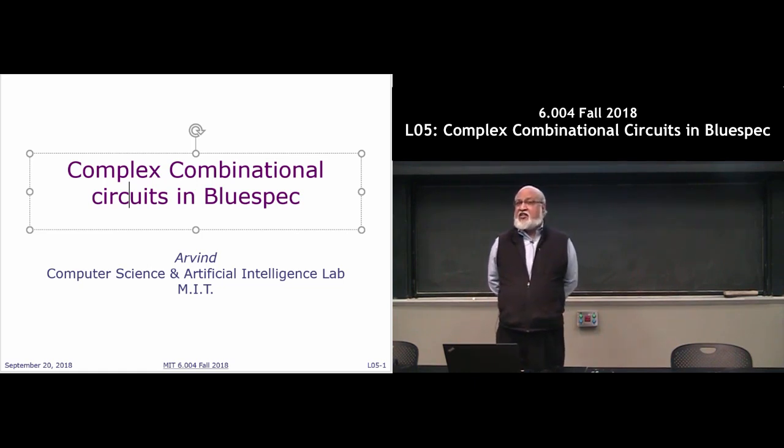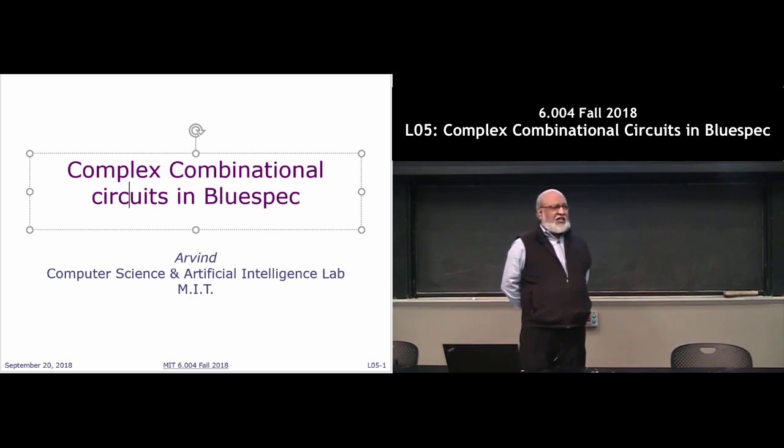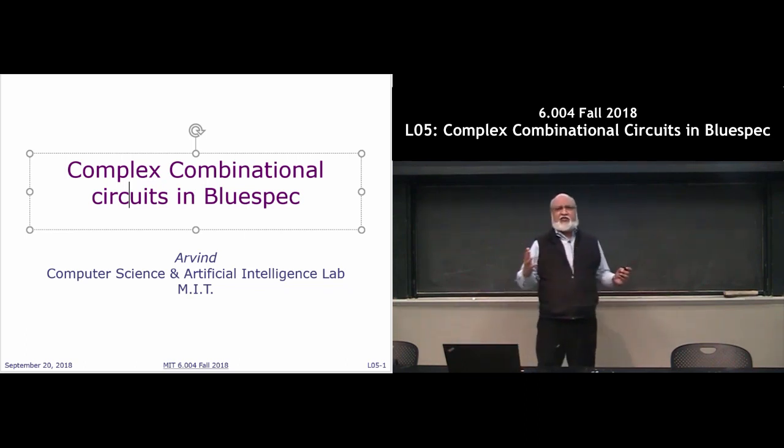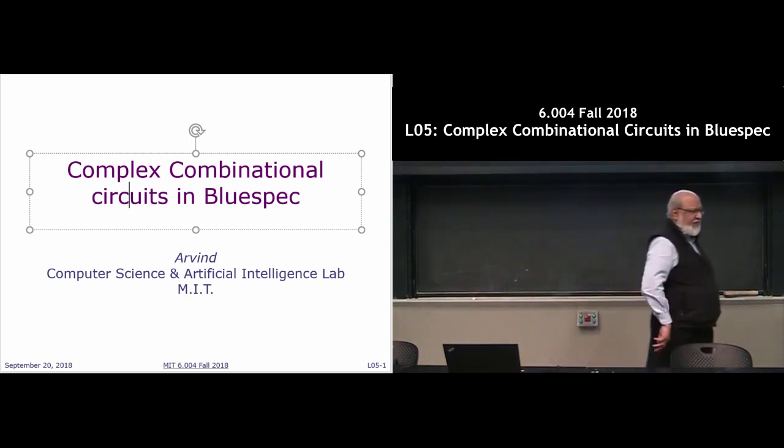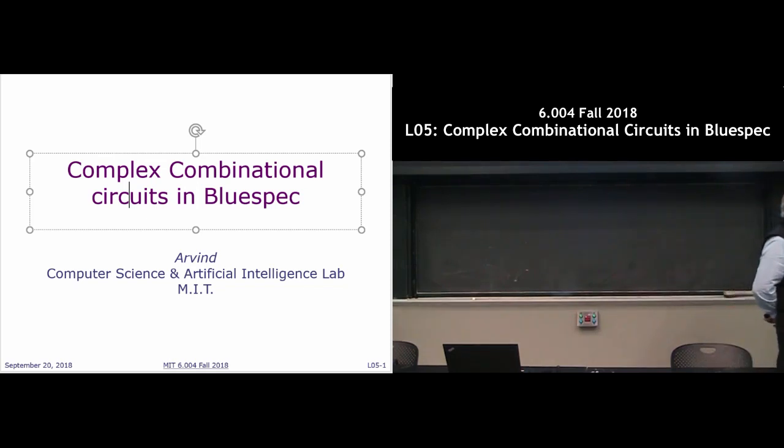Any time I write a loop in Bluespec, and there is no exception to this, it's always unfolded at compile time. So if we make function calls inside a loop, that either creates a circuit or, by cycles, uses a circuit already created, right?